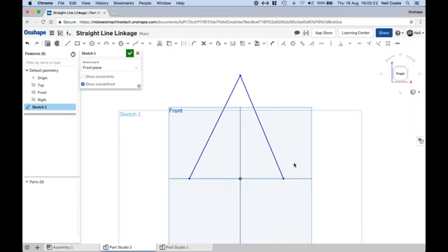What I mean by that is that you would add the link length in for the position in the middle. Because obviously, if you just go from one point to the other, the natural shape is going to be an arc. But if we specify the middle location as being vertical, horizontally constrained to the origin, then it gives us 3 positions to control that shape.